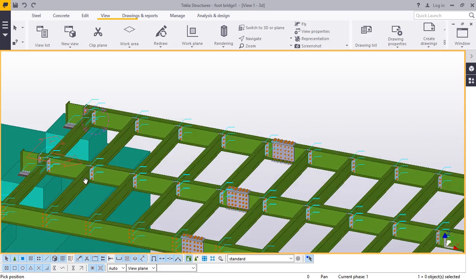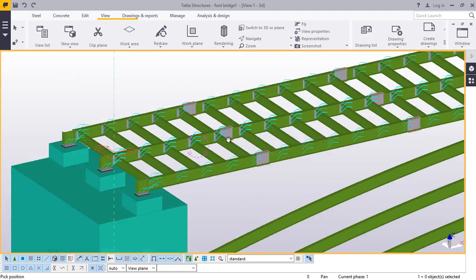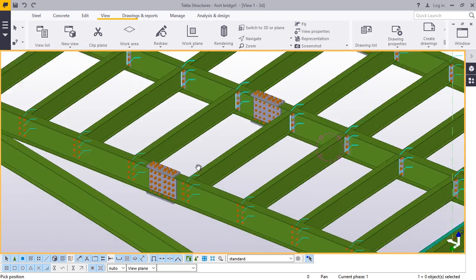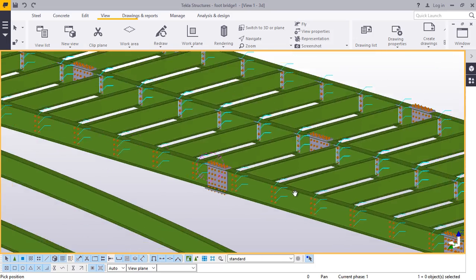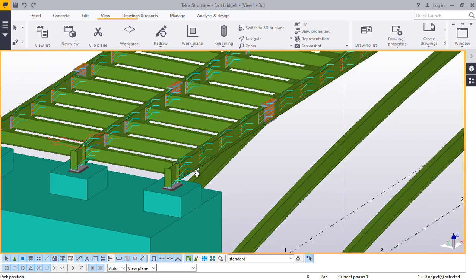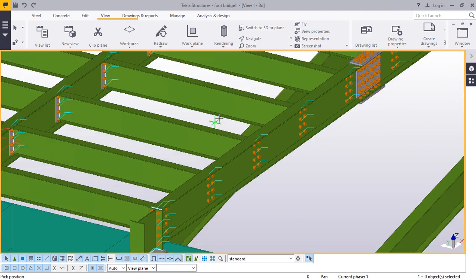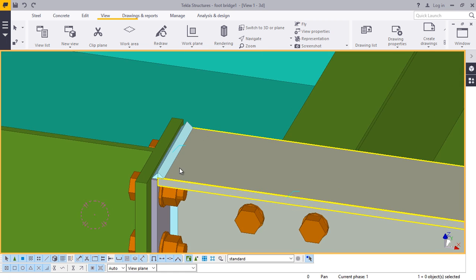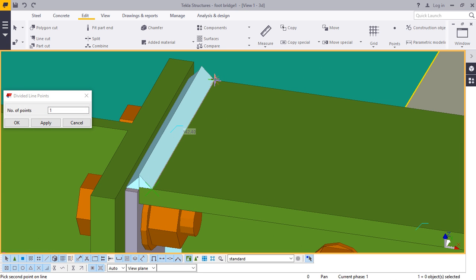Turn this round. Our footbridge is coming closer and closer. Navigate, try to rotate this. Now next thing is to place our handrails, but prior to placing our handrail we need to place some guidance here. We'll snap there and snap here.